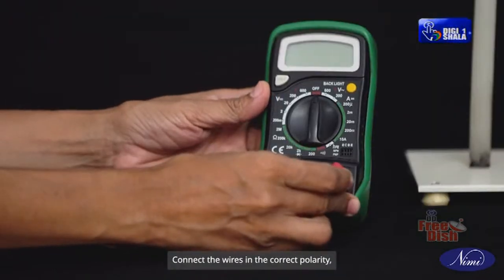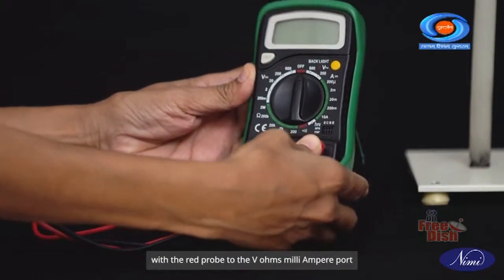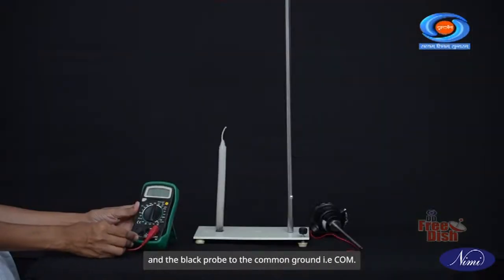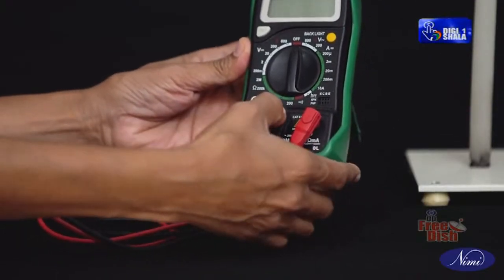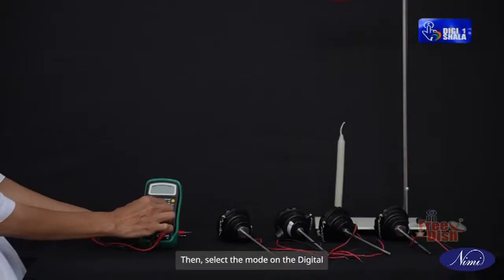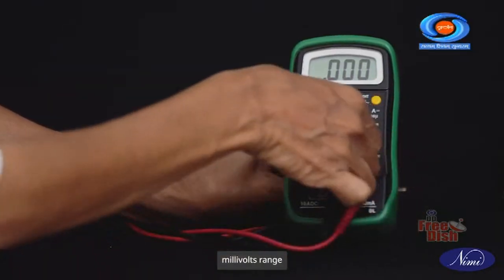Connect the wires in the correct polarity with the red probe to the V ohms milliampere port and the black probe to the common ground, that is COM. Then select the mode on the digital multimeter to display in the low DC millivolts range.